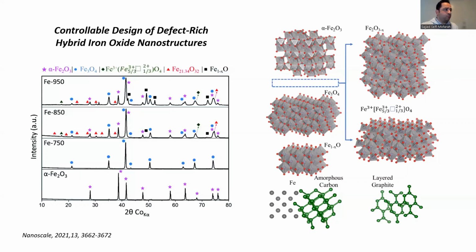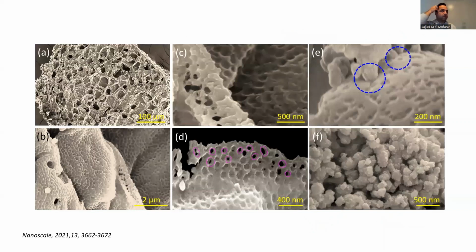All right, so as I said, the materials we have were hematite as a precursor and carbon-based waste materials. Because we had waste materials, we had impurities in these materials, and one of the impurities was potassium. And during oxidation and heat treatment, that potassium transformed to potassium oxide. And during rinsing of the sample after heat treatment, potassium oxide washed away from the sample, leaving behind perforations. So what you see from the SEM images in this slide is the perforated structures of the carbon-based materials we have.